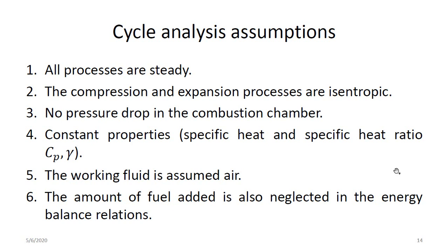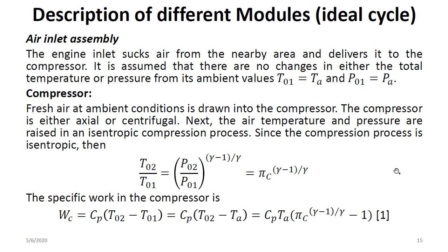And the properties are constant, that is the specific heat and specific heat ratio. And the working fluid is assumed to be atmospheric air, and the amount of fuel added is neglected in the energy balance. So this assumption will help simplify the analysis.